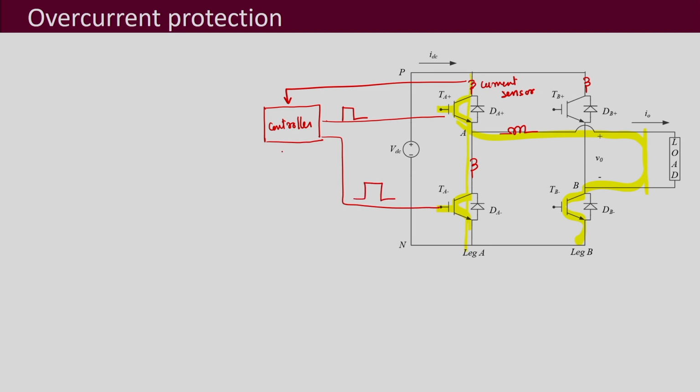But obviously there will be a delay involved here, because it takes some time for the current sensor to sense. The sensor itself will have its own delay. Then your controller will decide what to do, that also will have its own delay, and then for you to shut down or stop the gate pulses, that also will take some time. So, this kind of arrangement will have some delay,